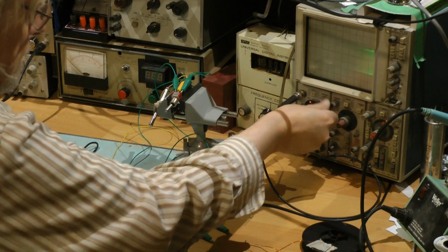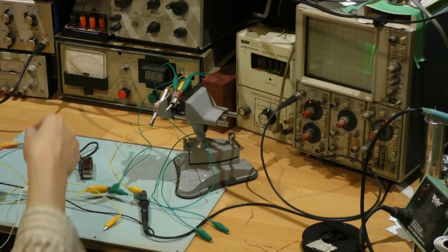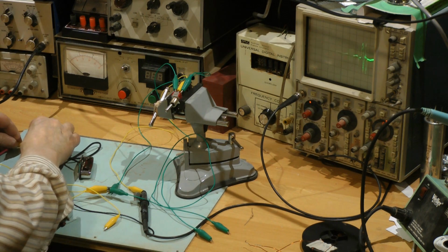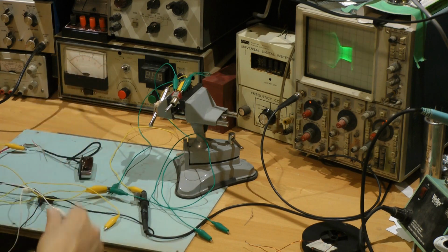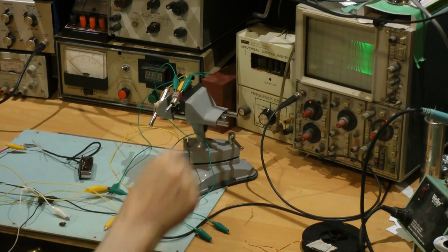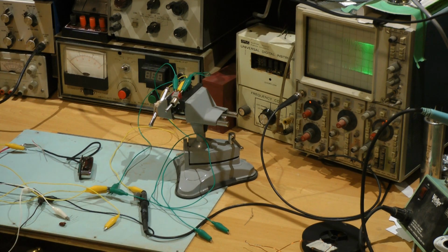Okay, now if I feed that through a tele pickup here, we can see the pickup doesn't like high frequencies and kills them off because of its inductance. The scope, by the way, is 1 meg load because I have the probe set to ×1. So that would have been your response if you had a perfect cable. In other words, no capacitance or anything in it. Most guitar amps have a filter to increase high frequencies.